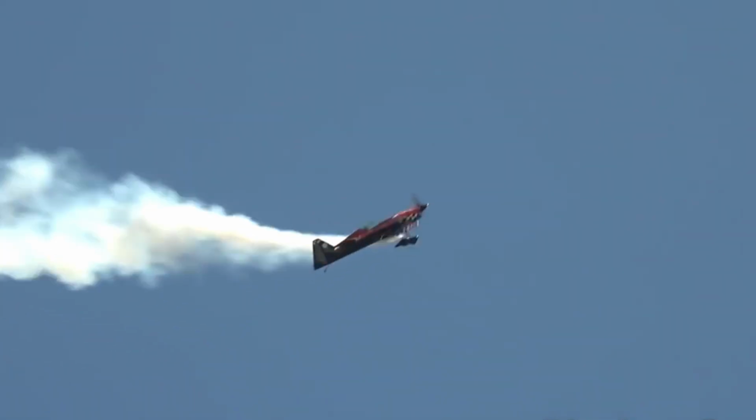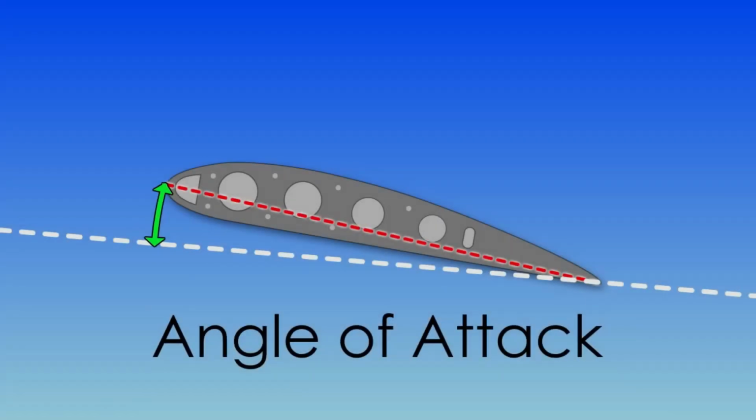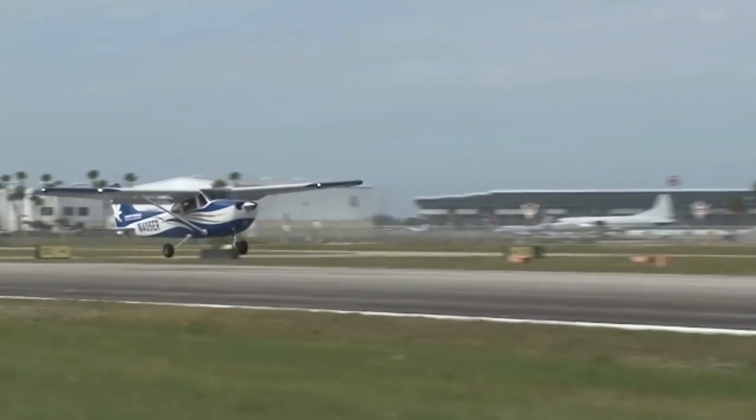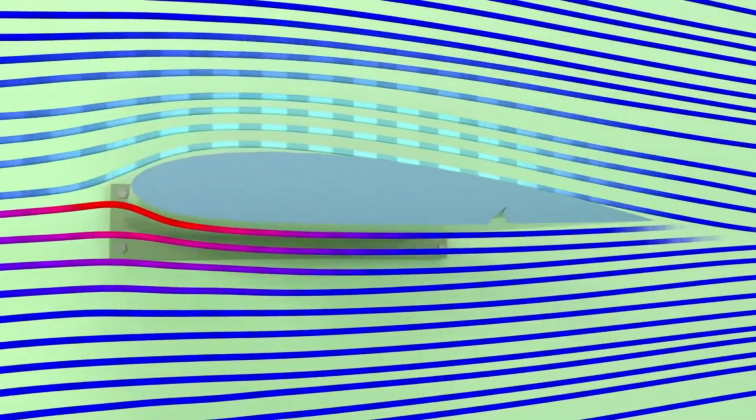Interference drag. Interference drag is generated by the collision of airstreams creating eddy currents, turbulence, or restrictions to smooth flow. For instance, the airflow around a fuselage and around the wing meet at some point, usually near the wing's root. These airflows interfere with each other, causing a greater drag than the individual values.